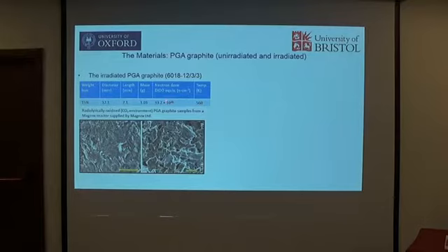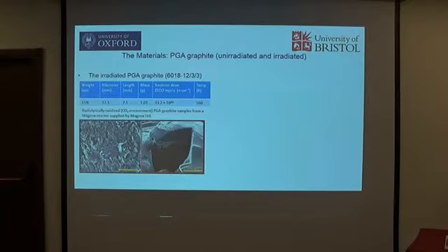For comparison, this is the matrix without irradiation, but after irradiation, there are lots of pores introduced in the matrix. This is because in the UK reactors, we use carbon dioxide, and that causes the material to lose weight. The graphite loses weight during the reactor service. Again, if you use a focused ion beam to cut into the solid regions, you can see the porosity we saw before. Before the irradiation, the pore has disappeared.